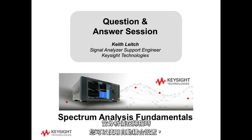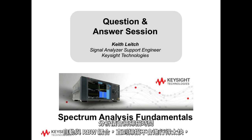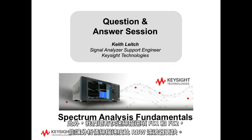So when the analyzer is sweeping and you're using the auto couple settings, the analyzer will auto couple the sweep time to the RBW so as not to sweep too fast. And then additionally, we do have the fast sweep options, FS1 and FS2, that allow the analyzer to sweep faster than the RBW filter would otherwise be able to sweep.